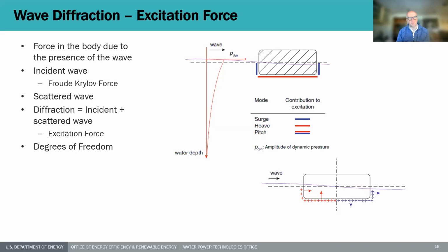These two terms, the incident wave field and the scattered wave field, are referred to as the diffraction wave field, or the diffracted wave field. And together they compose the excitation force that drives the system. I should mention that literature is a little bit at odds with the definition. In some books, you'll find that the scattering is the superposition of the other two, but the principle is the same.